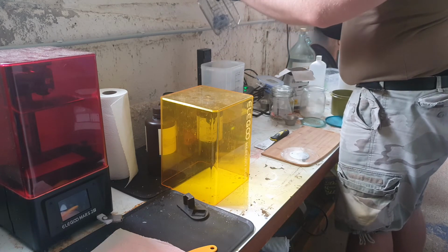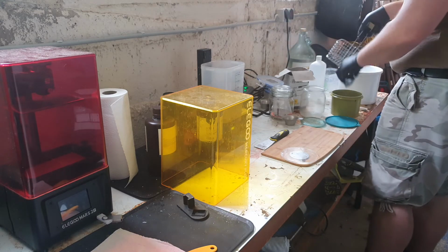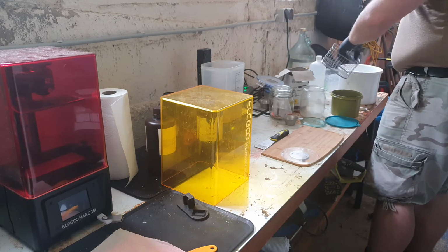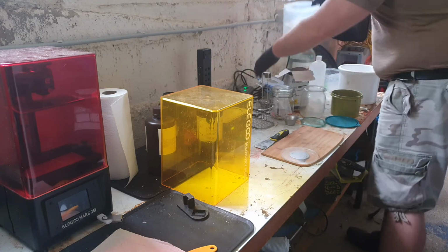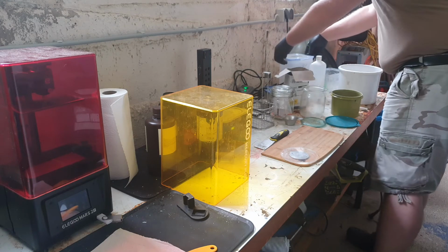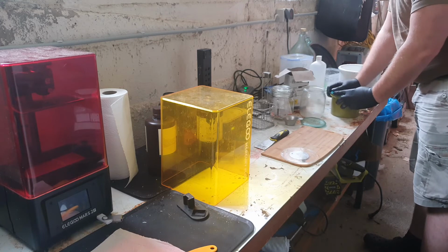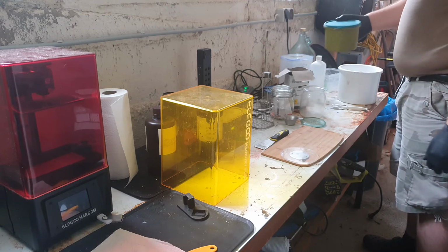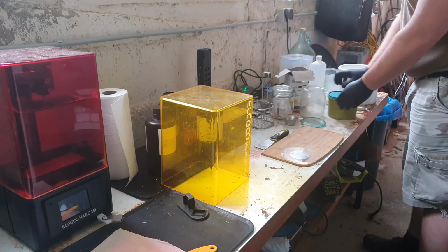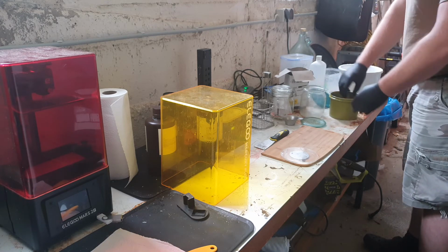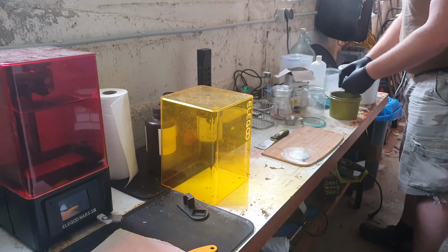First, I wash it with the machine, so to get most of the leftover resin off. Then I wash it by hand in a second container with cleaner, fresher isopropanol to get even more off. And then, when most of the plastic resin, or hopefully all of it, is off, I wash it in hot water. Not to wash it actually, but to soften it up, so it's easier to peel the supports off.